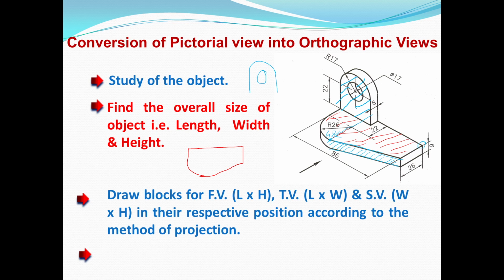So for this surface we get the true shape, and the dimensions are equal to the true shape dimensions, whereas for the projected view the dimensions are different from the true shape, and they are less than the true shape.